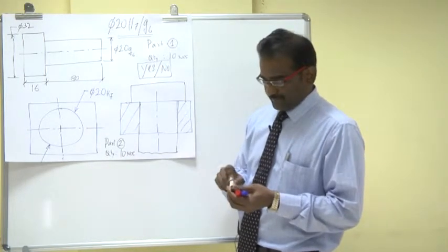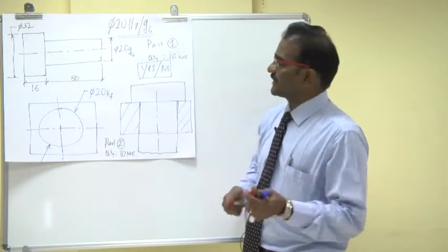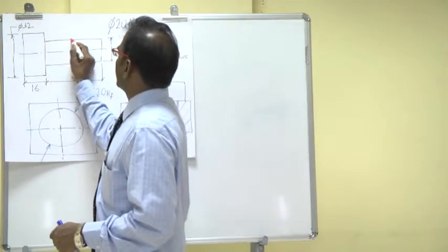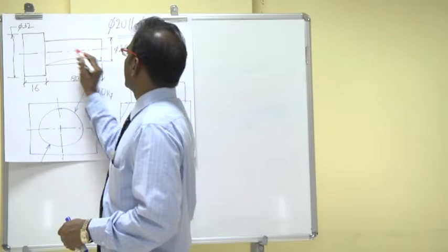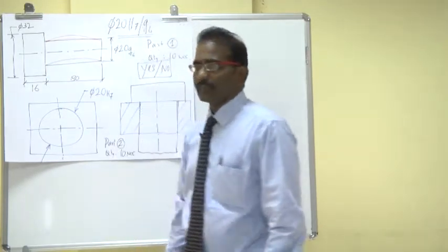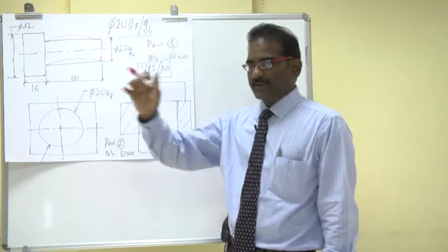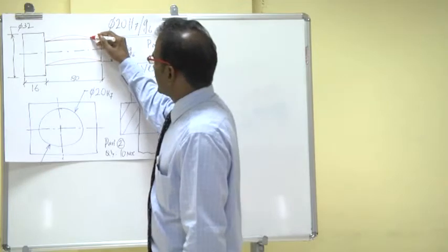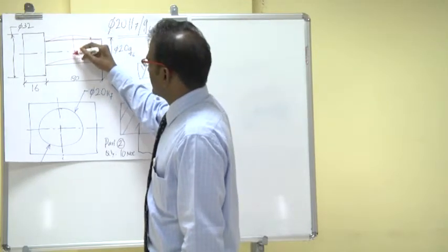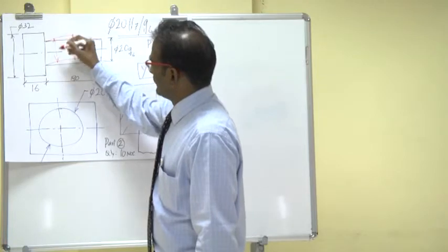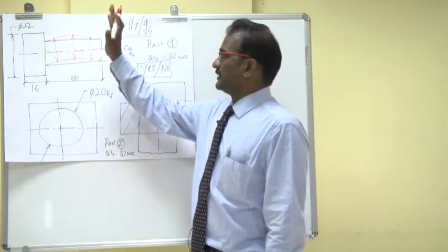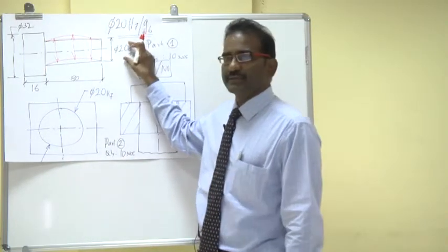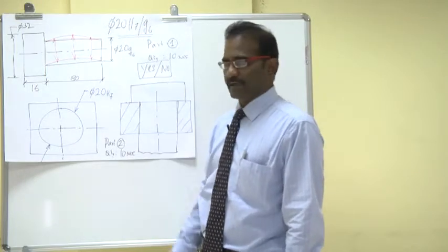Let me explain. Let us say the shaft is having a little bit of bend on the diameter 20 portion. Instead of being straight, it is having a convexity or bent along the axis. Now, while checking for the diameter, there could be chances that at individual sections, the diameter I am getting is within the stipulated tolerance of dia 20 G6.